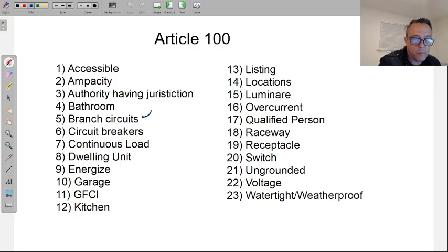So a circuit breaker is one of these devices that go on and off, so we want to turn them on and off when we want to energize and de-energize the circuit. But while the circuit is on, if anything happens to those wires or the thing that somebody plugged into or the outlet sitting there, short circuits and ground faults and overloads, all right, we'll get to overcurrent, which is all 3 of those things, then you want the breaker to respond. You want the breaker to trip and respond to that fault, as we call it.